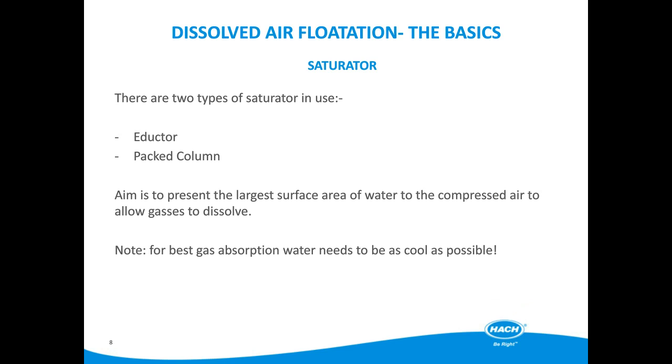Moving on to the saturator. This is an important part of the DAF process, as this is where the formation of the microbubbles which lift the floc begins. In general, the normal flow rate through the saturator is around 10% of the inlet flow, but on a highly loaded DAF tank, this can be up to 100% of the inlet flow.